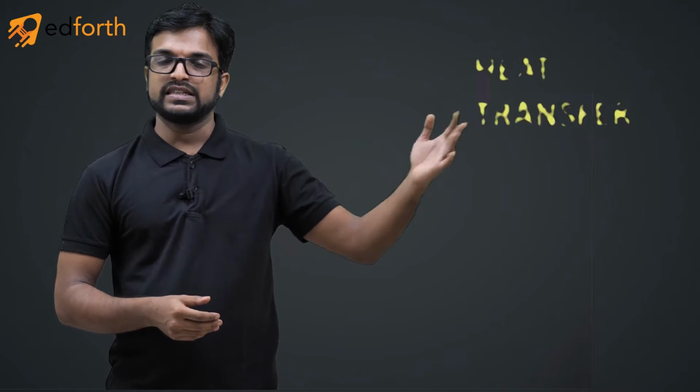That was pretty straightforward. Let's move on to the next, that is energy in transit, which is very important from a thermodynamic student's perspective. Let's understand that. In the case of total stored energy, we are seeing that these are the energies which can be stored inside the system. What do you mean by energy in transit? These are nothing but energy interactions between system and surroundings. This sort of energy cannot be stored inside the system. There are two types of energy in transit, work transfer and heat transfer.